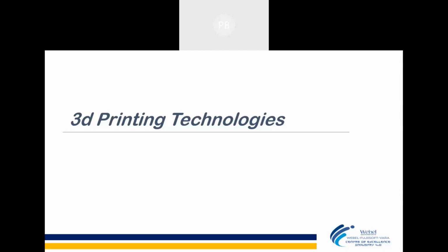But this disadvantage comes up only with FDM, because FDM provides only XY dimensional strengthening. With other kinds of technology, which we are going to learn now, the different technologies of 3D printing, whereas with SLS, whereas with SLA, this provides uniform strength, which is an isotropic strength property. So in this part, you don't need to worry about layer thickness and layer directions. Here you will get isotropic properties, because these are liquid. Here layer marks will not be there. Whenever there are layer line marks, that is an FDM part, which is a disadvantage.